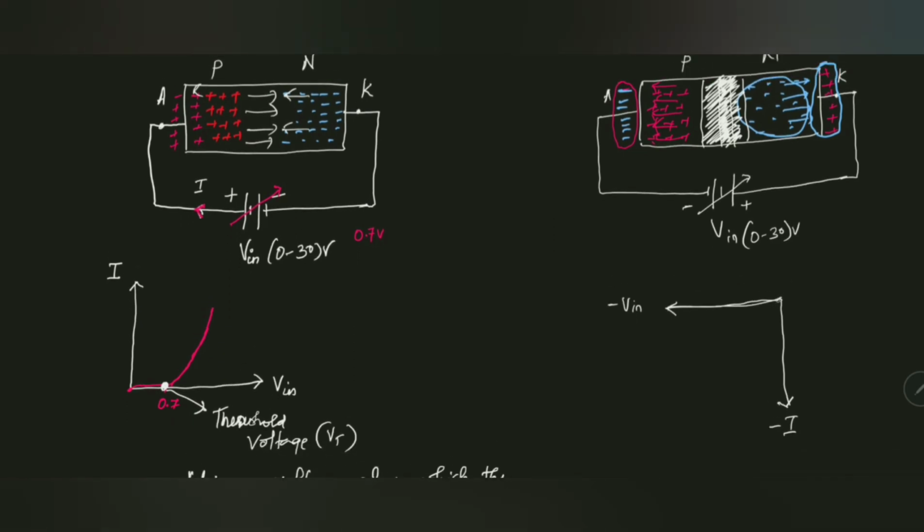So what happens, from the point of 0, as the voltage increases, there will be a very, very small value of current, until at a point where the voltage is negatively increased to a very great value, immediately the breakdown occurs and the current starts to increase on the negative side to a higher value, keeping the voltage constant. And this point is now called the breakdown voltage. It's called the breakdown voltage. It usually happens in the reverse bias.